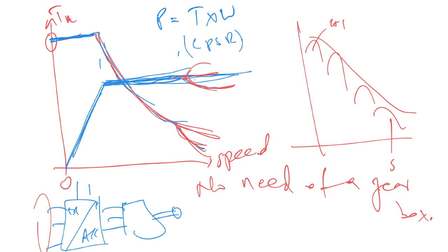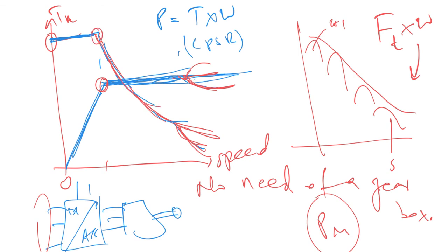So what we had obtained with your tractive force at the wheel, remember, we were now able to translate that to the power in at the motor side, right? That power rating, it's this point. So you rate the machine at this point, just before the torque starts to almost not collapse, but to decrease.